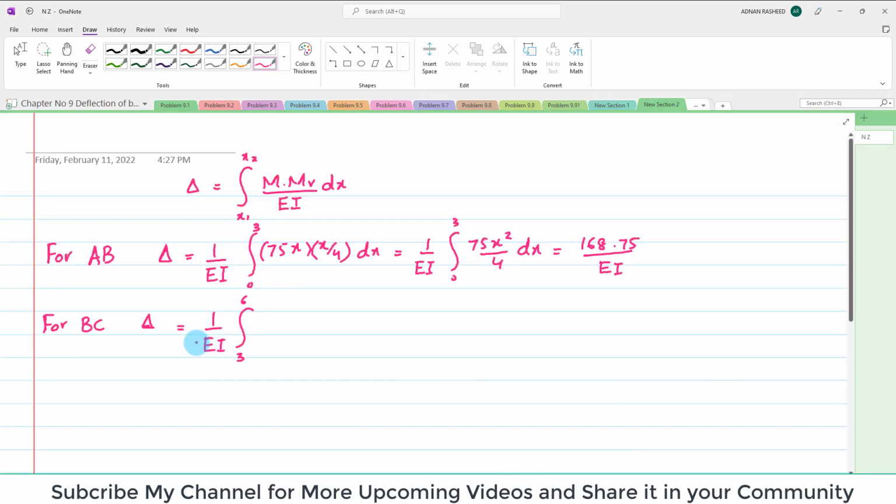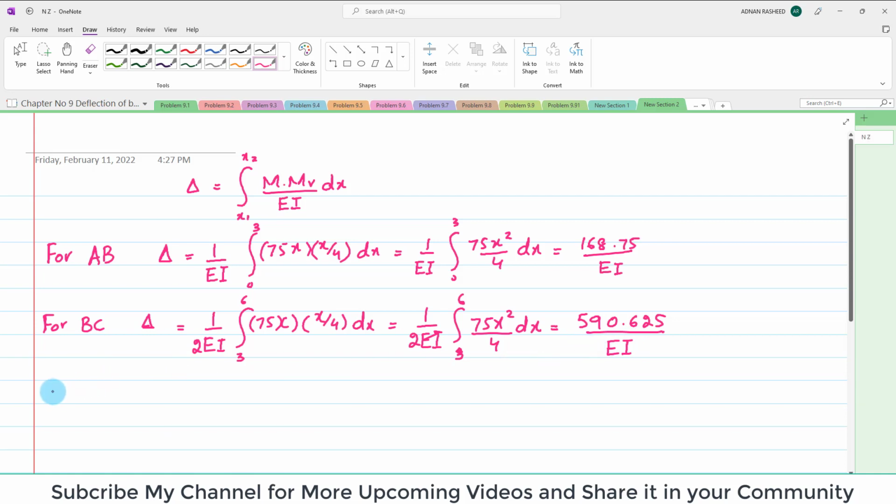So you have to put it 1 over 2 EI, and the rest: this is 75, m is 75x, into mv, which is x by 4, into dx. So again it will be 1 over 2 EI, integral of 3 to 6, and it will be 75 x square over 4 into dx, is equal to, when you take the integral of this and put the limit for x, you will get 590.625 divided by EI. When you simplify it, you will get this value. You can check it later.